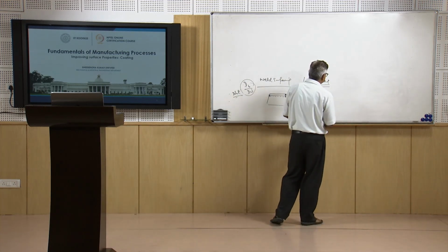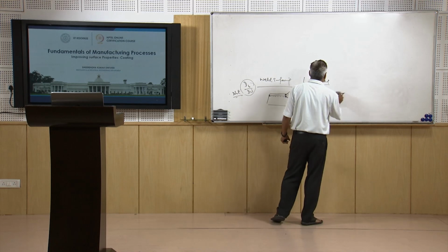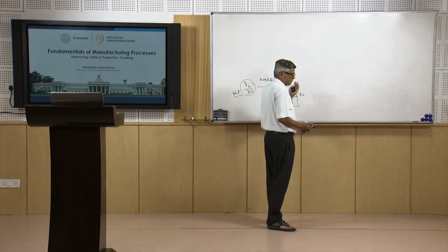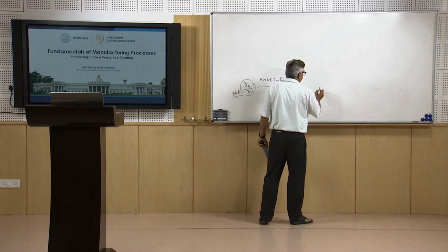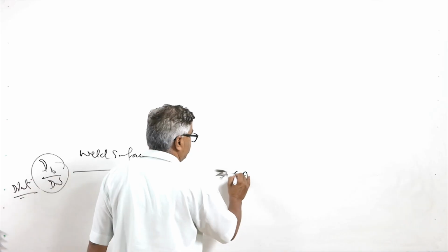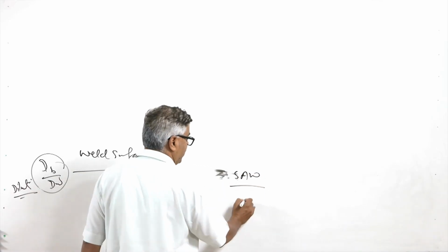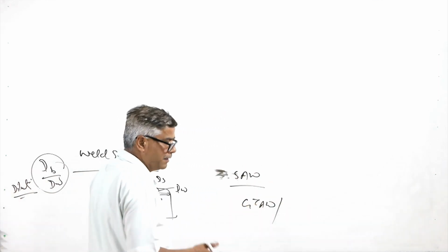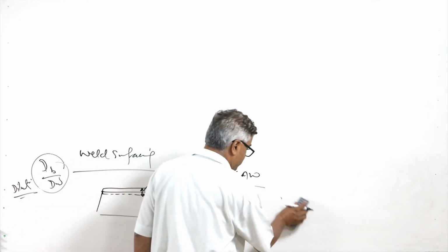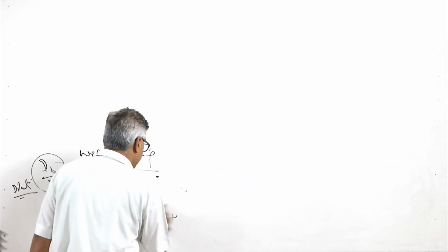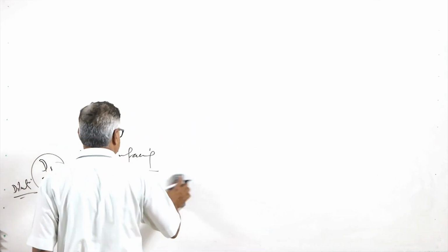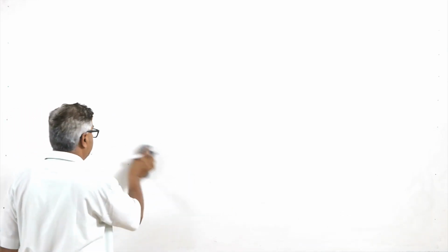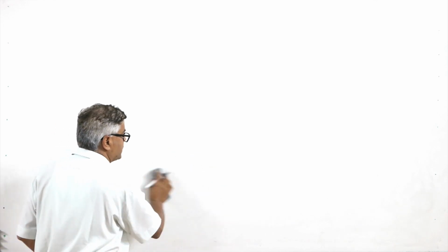High energy density facilitates the melting of the coating material and limited melting of the base metal, leading to lesser dilution as compared to common welding processes. High dilution is encountered with processes like submerged arc welding as compared to GTAW, where filler is fed separately because this process uses a non-consumable electrode. So, as per the kind of process we are using, the heat input and the cleanliness of the weld will be different in weld surfacing.